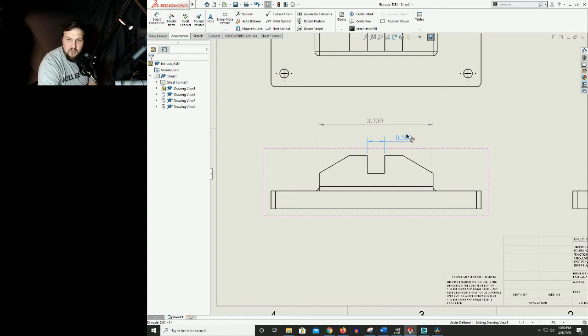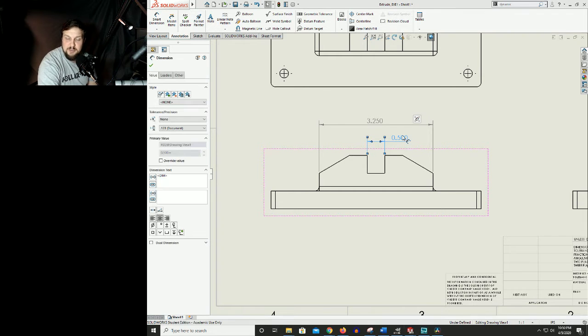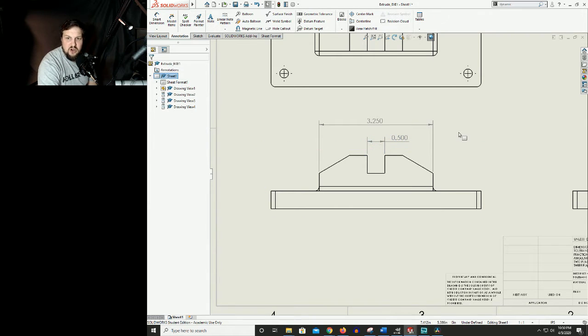We don't want that. We want nice, cleanly spaced dimensions that are well separated so that they don't look like they're running into each other. They are well laid out so that they're easy to see the components. And as rarely as possible, we want the extension lines to not pass through a model view.